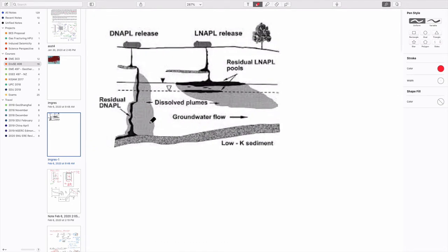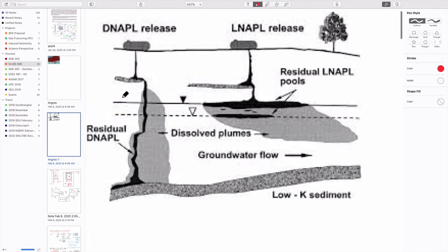Well, today we'll talk about mobility of solutes in the vadose zone. And so far, to put this all in perspective, in looking at the behavior for our system, what we've done is we've looked at the behavior in the subsurface to where the fluids go over the first few days to weeks, how they're held in place by interfacial forces and don't move. If they do move, it's controlled by relative permeabilities.